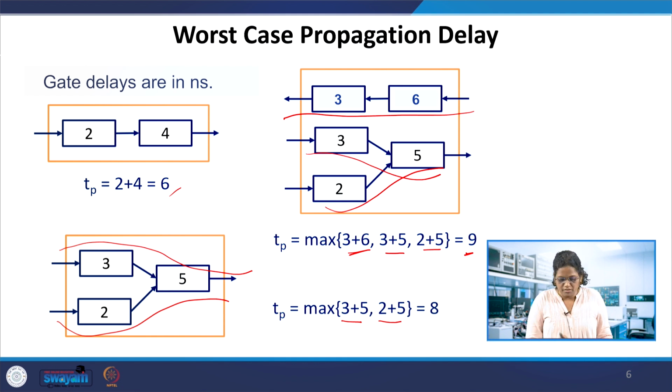This identifies the worst case propagation delay, also called the delay of the critical path. The critical path is the longest path between the input and output through the logic circuits which have been designed. For the adders, multipliers and the examples we had done, we can calculate the critical path with the logic circuit also.